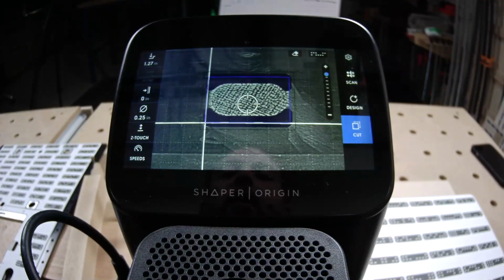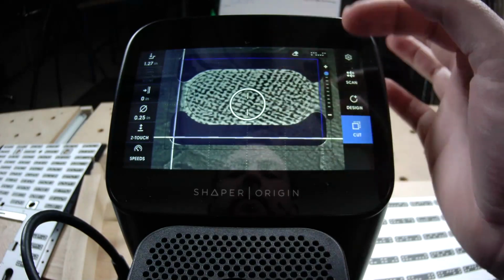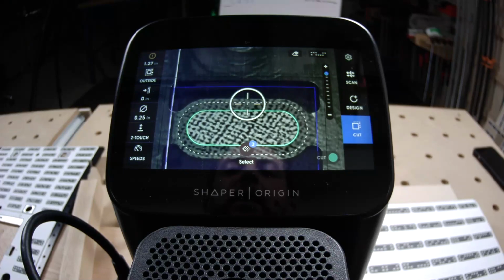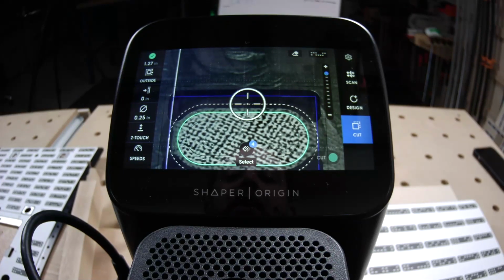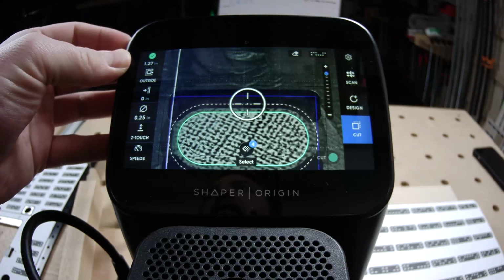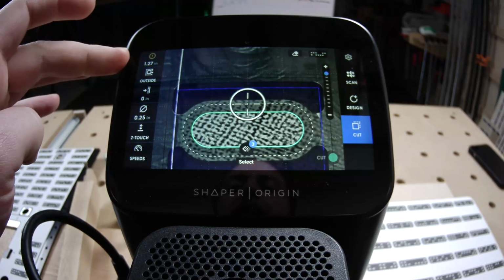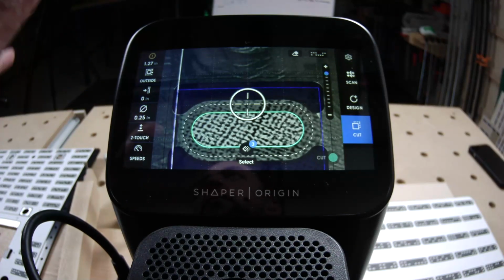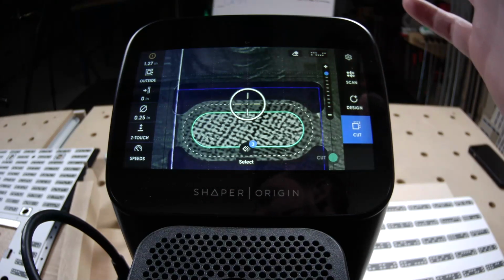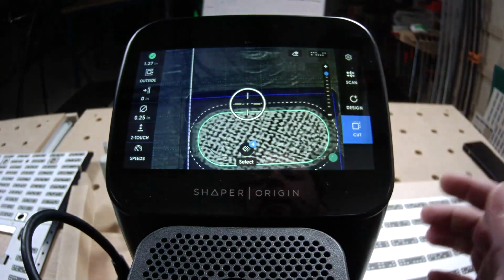Exactly. All right, so I've gone ahead and already cut some of the pockets just to get rid of that. But if you notice, I have two paths here. My smaller tenon and a larger tenon down below. My current depth is set to 1.27 inches. That's my final depth. If I try to cut this inside, boom, it's going to give me that big, bold exclamation point saying, whoa, that's too deep for this particular path. Do not plunge. And if I go over here, I get the green check mark, and I know I'm good to go.